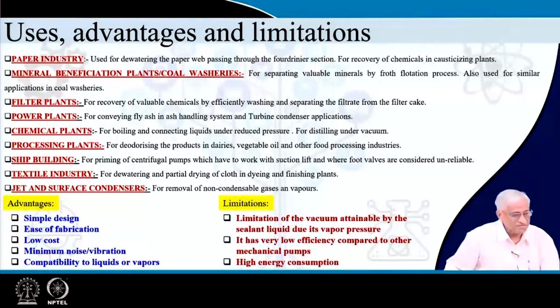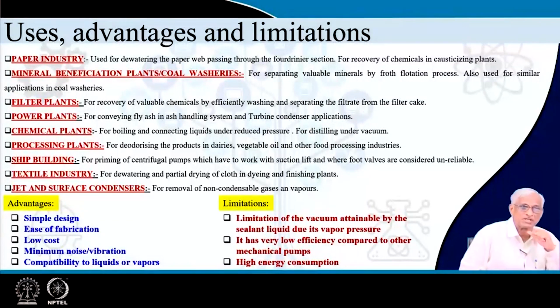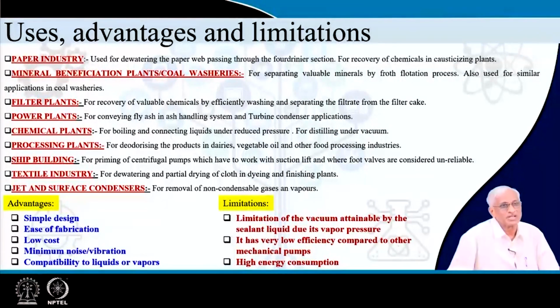So, after getting a feel of this water ring pump, its capability to produce 30-40 torr using a simple mechanism of water, without much friction, without any mechanical contact between two solid materials, and using very simple inexpensive water. So, the working fluid is very cheap. That way, the cost of this water ring pump is not much, and repairing is also quite easy.